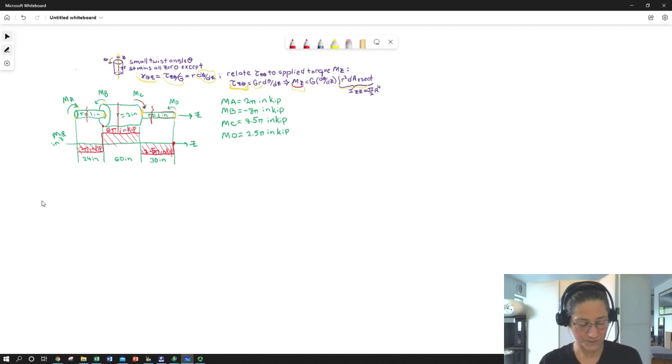This will be even more useful if you had a little bit more complicated and interrelated problem like a beam, where you have several loading modes that matter. One nice thing about torsional shafts is we really only have one direction we worry about. And in this case, we're not going to be worried about fracture. So when we get our tau z theta, we'll be comparing that to material yields.